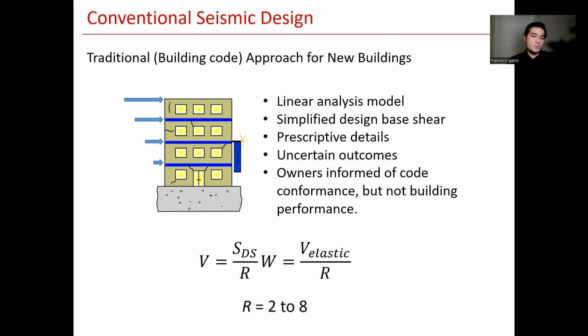Which in other words means that when the design earthquake happens, the building would be expected to be severely damaged, with a really high likelihood of required demolition, right? So all of the patrimony, all of the investment would be lost, but the building would theoretically provide enough time for occupants to evacuate and would therefore save lives, right?